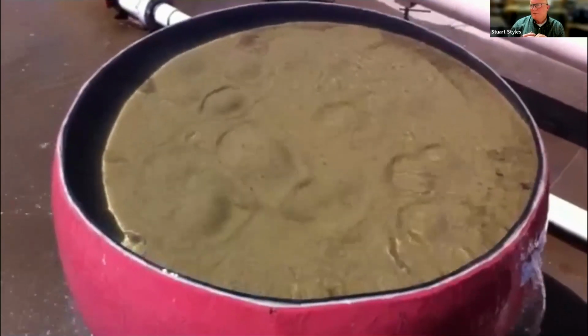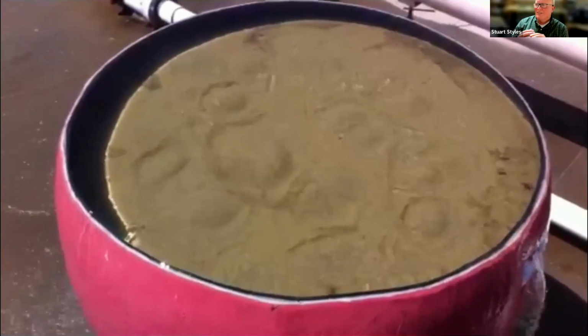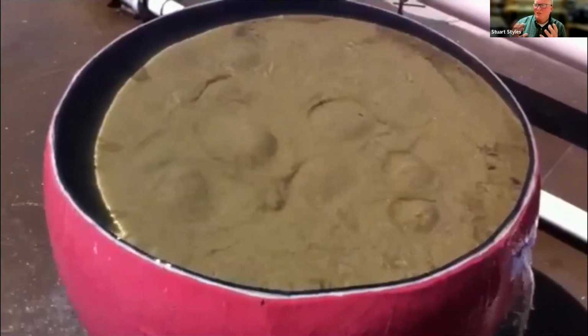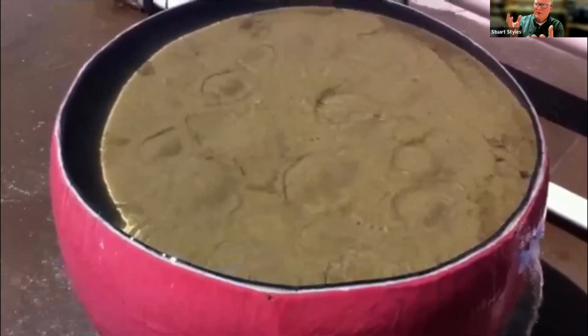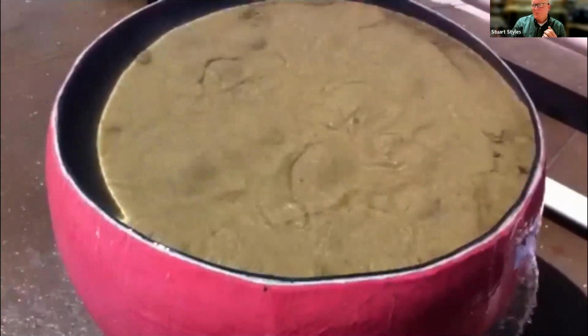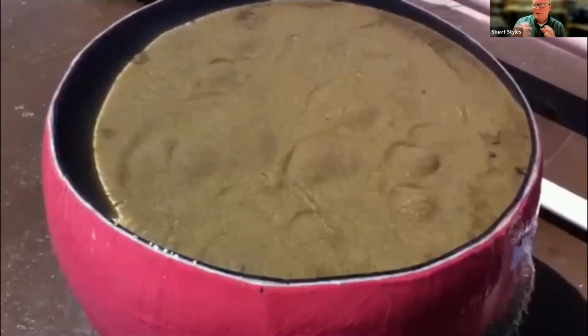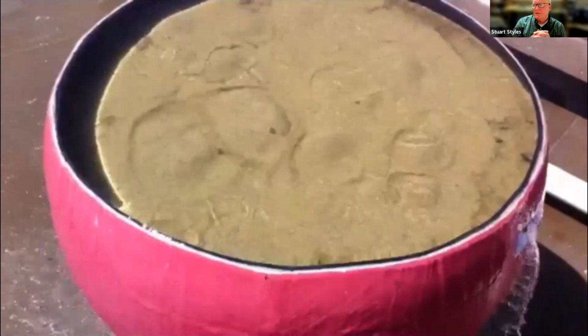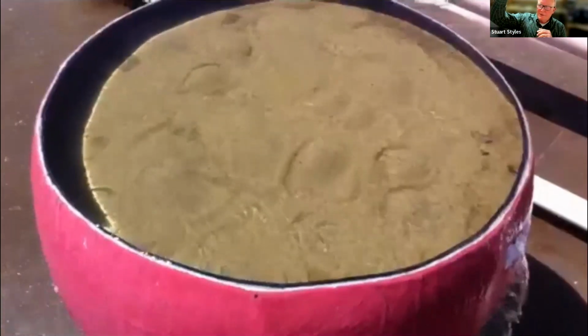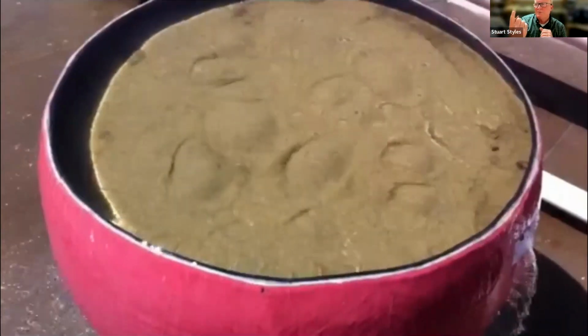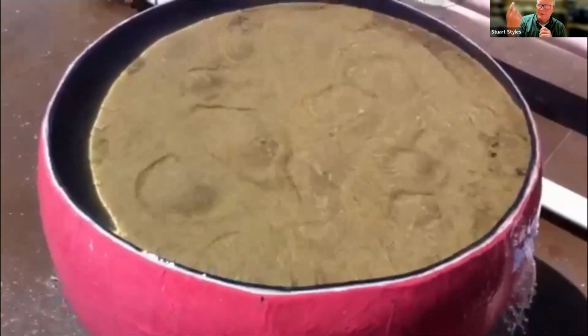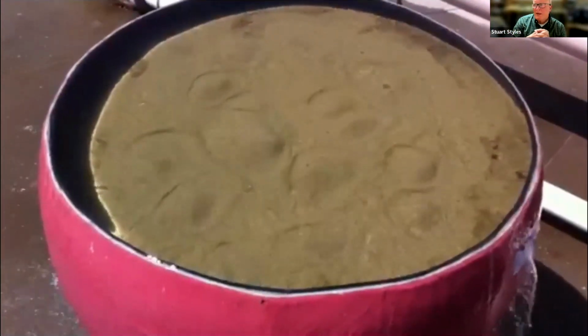So this is a video. I'm hoping it's coming through here. A short video of just showing that bubbling action or that boiling action. Where it's boiling, that's a good thing because it's getting a lot of flow and it's going to clean out the material that was caught in the sand media tank. Normally the flow is down. So this is in the backflush mode and it's pushing the debris up and through the backflush line.